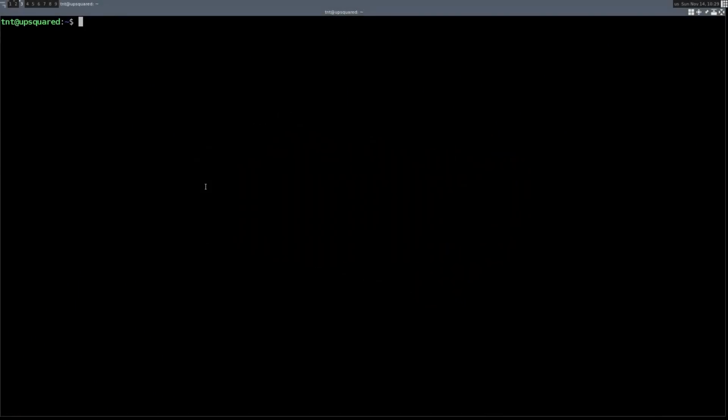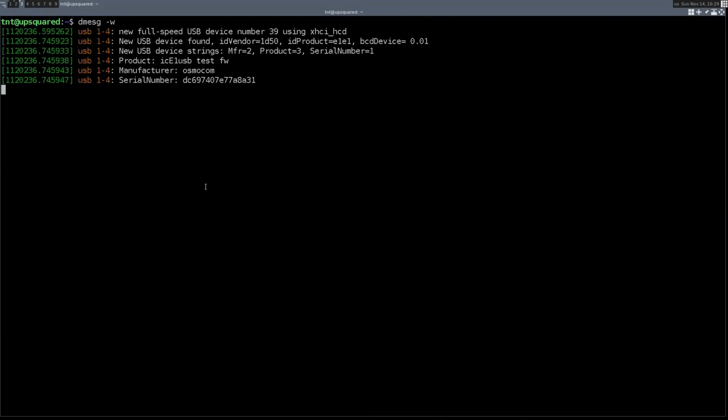Moving on to the actual usage part. The first thing to do if either the device is new or hasn't been used in a while is to upgrade the gateway and firmware to the latest version. Brand new devices will probably still have the factory test firmware loaded, and although it gets recognized as a USB device, that firmware can't operate normally.